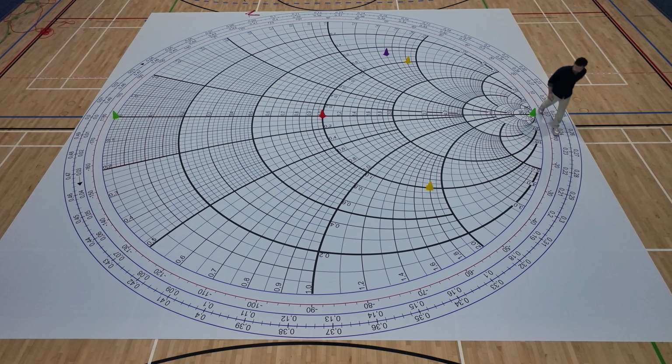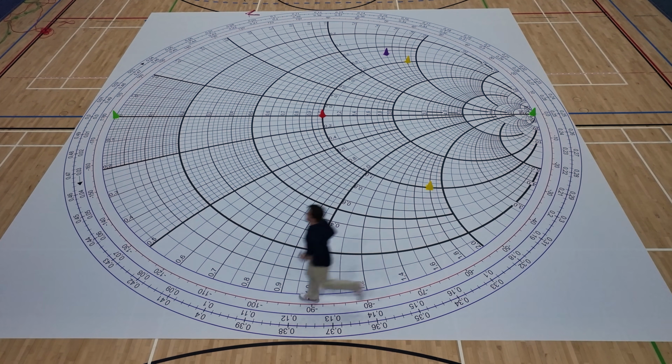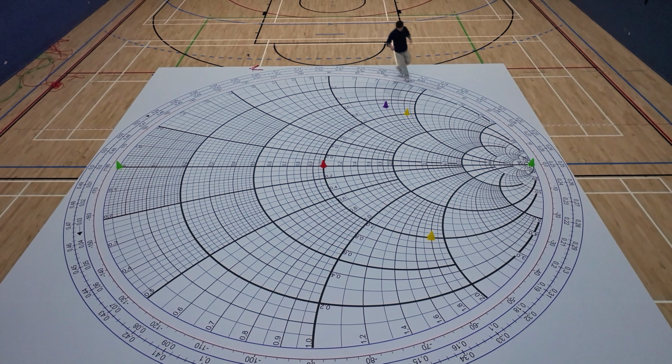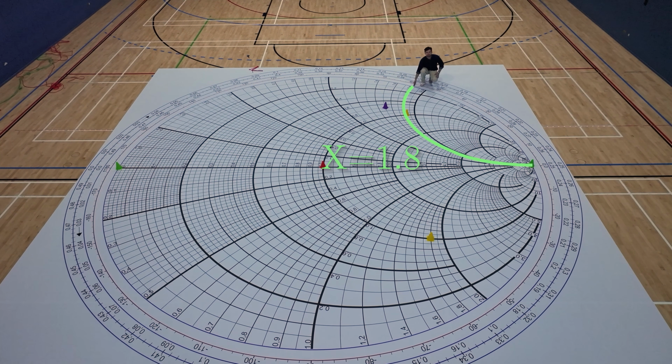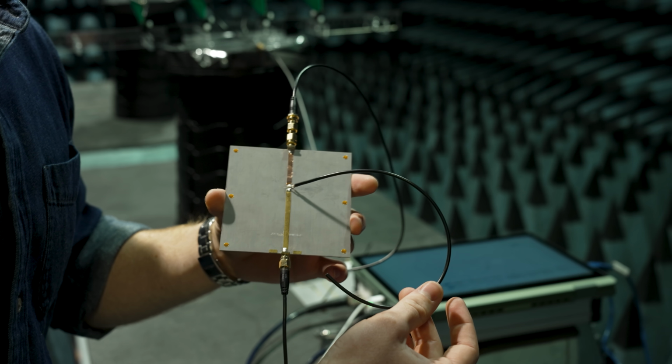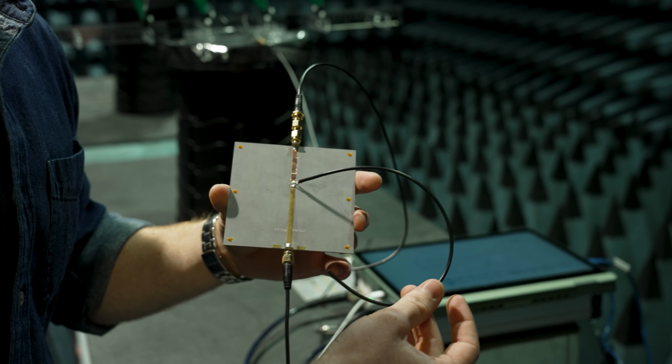So we start at where the open circuit is and walk all the way around our chart. And we stop at 1.8. When we measure the angle, we see that that's about 302 degrees. Okay, now 302 divided by 360, that gives us how far along we've been on the circle, and we know that one full circle turn gives us half the wavelength. We get 77 millimeters. That should be the length of our stub.